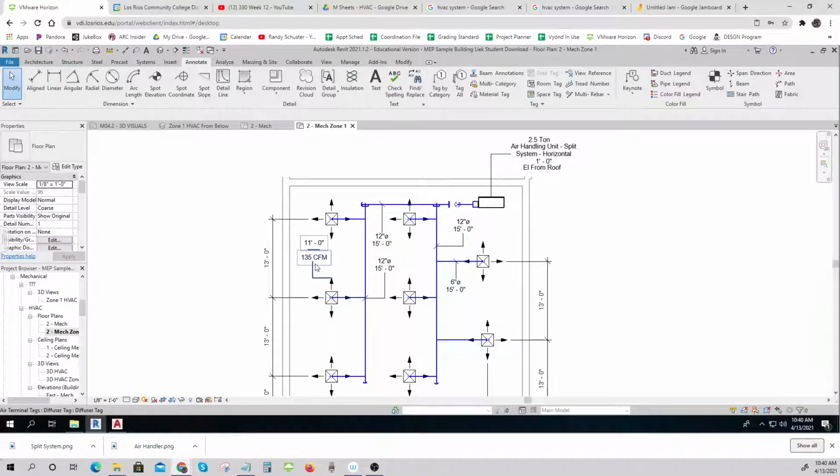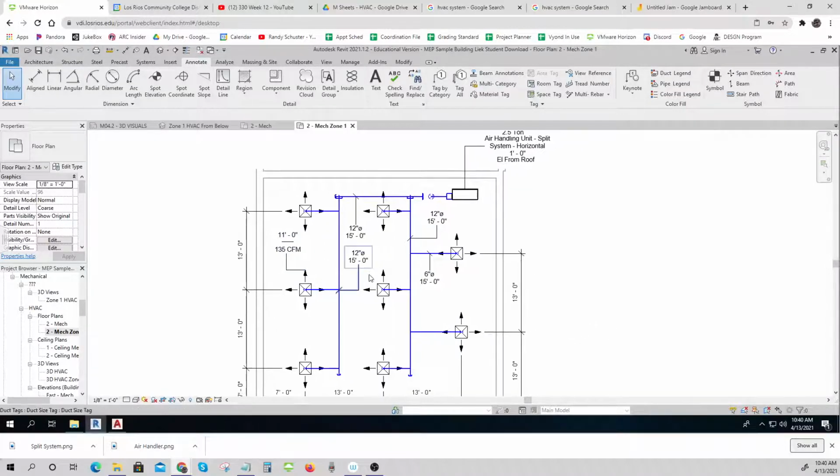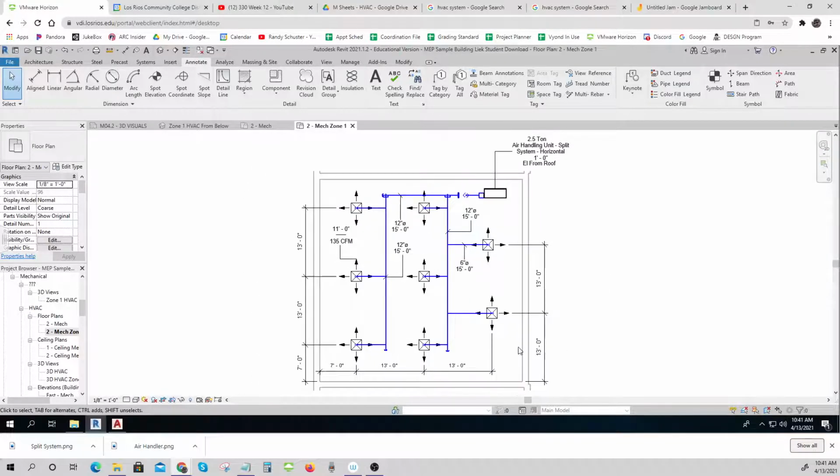It tells me about each one of my air terminals that are 11 foot from level 1, 135 CFM. And this little thing here says it goes in all 4 directions. And this is telling me that I've got ducting that's 12-inch diameter, and it's at 15-foot center line. So that's basically it. And it gives approximate locations.